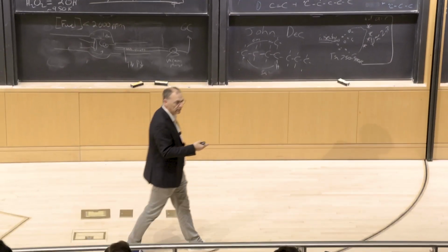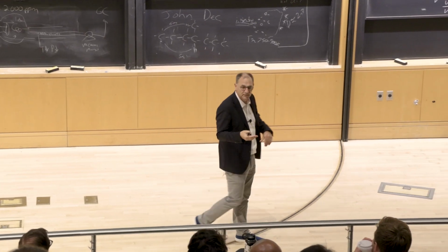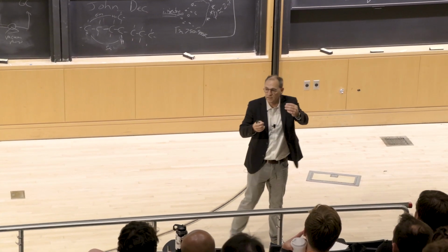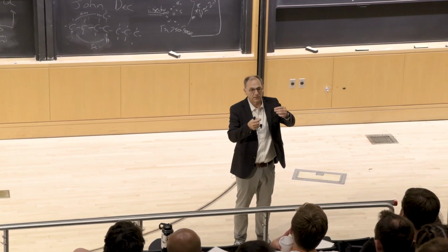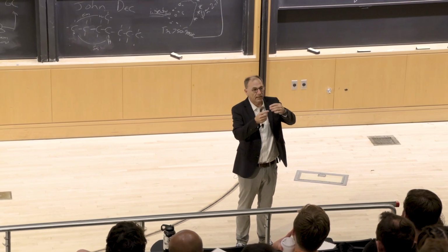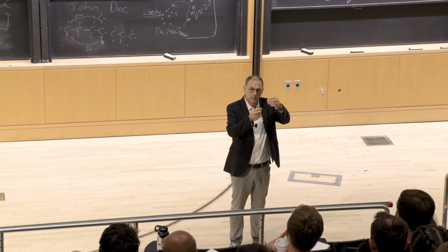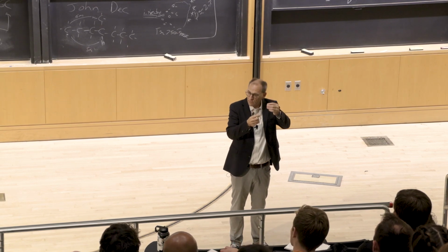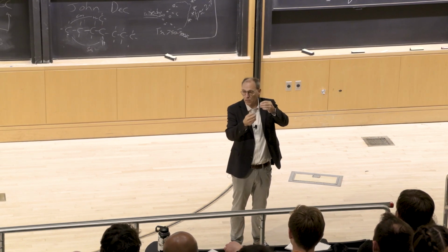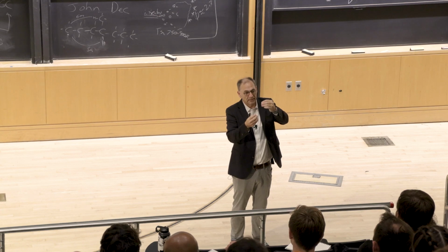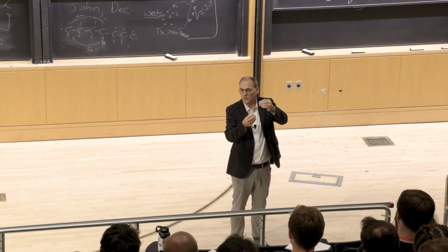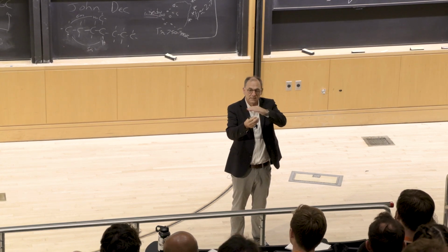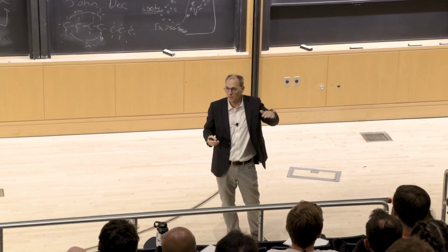It appears as the dissipation in the variance model. What is dissipation of variance? It basically means, if I have a variance in the mixture fraction, that means I have a region maybe where I have a little higher mixture fraction, and sometimes I have a little lower mixture fraction, okay? That's variance. And if that variance goes away, it basically means at the end everything is well mixed.